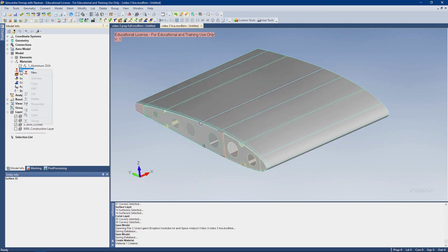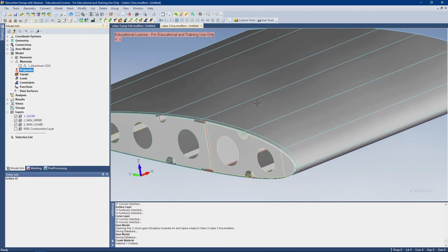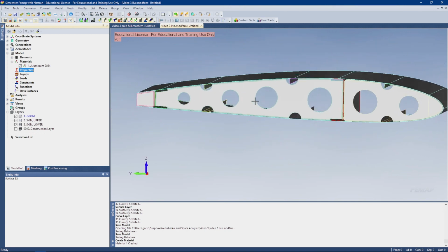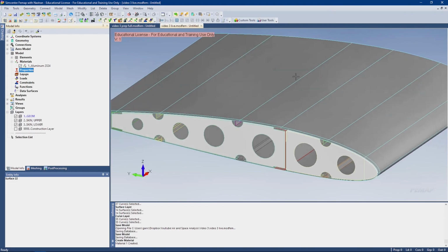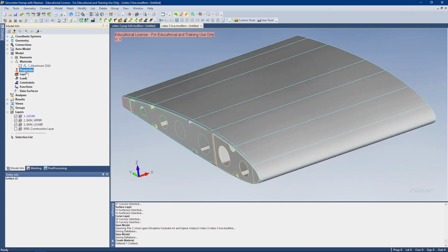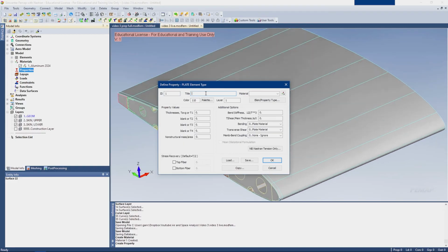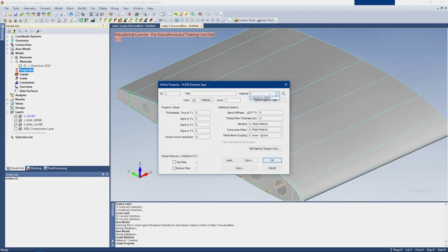Okay, now we want to use this property. So we're going to be doing a plate mesh, which is essentially you give it 2D surface geometry, which you can see is all we have right here. And with that 2D surface geometry, you have different properties; inside the card there's a thickness associated with it. So then you essentially generate something that approximates 3D geometry with 2D elements.